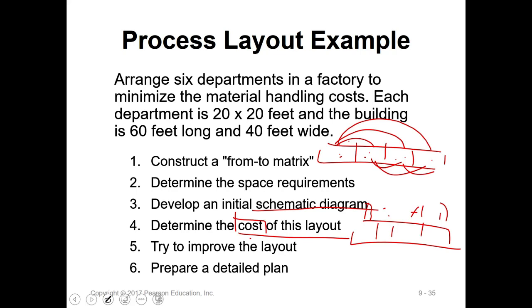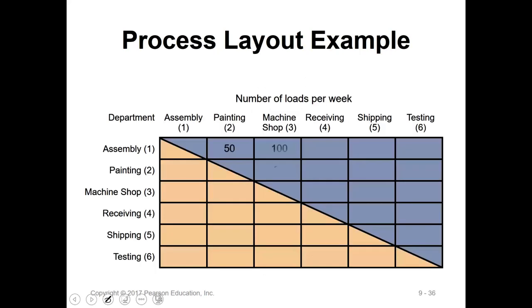When you plan the new layout, you can think about AB, which has a light layout, a small material handling need. Then I do not really care about AB's distance so much. If AC has a very big material handling requirement, I want to make sure my A and C are always put together. So that's the basic idea.